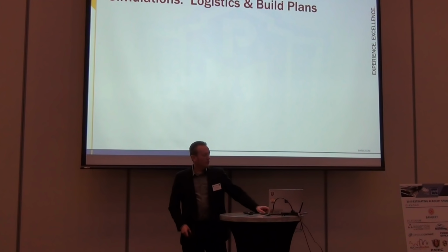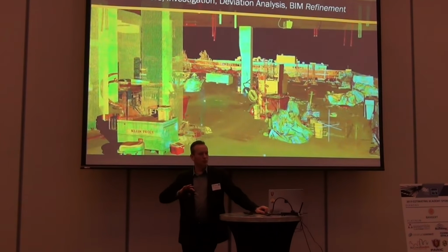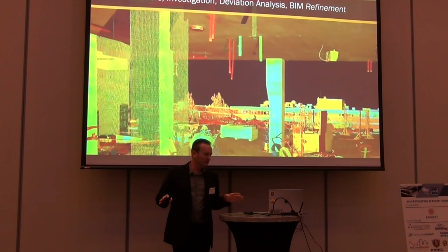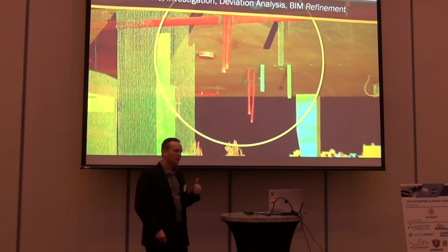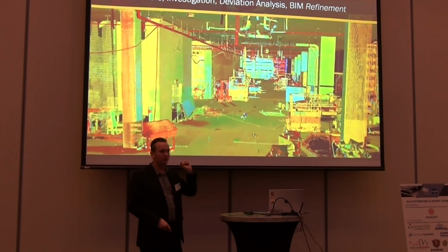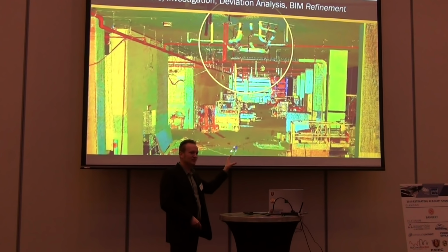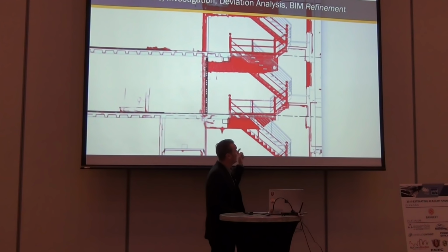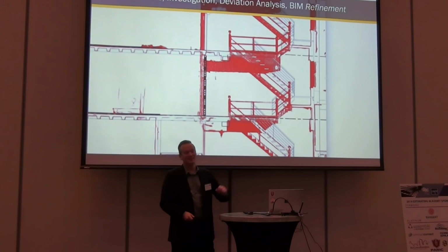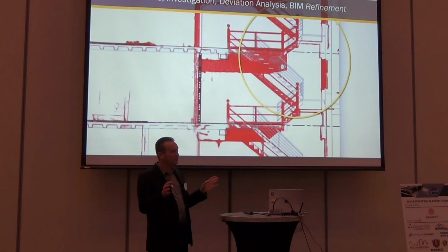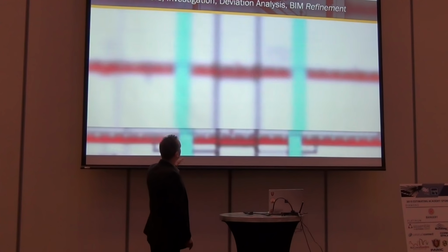So we get into these historic projects. New construction is fairly easy when you consider the variables that you have to work with there. But when you're in historic, it's a whole other thing because this exists. You've got to figure out how you're going to fit everything you want in that box, right? And on a historic building, I don't know if you guys run into this, but not every floor is the same. The columns kind of meander a little. The structural grids kind of meander a little. Stairs aren't exactly the same.